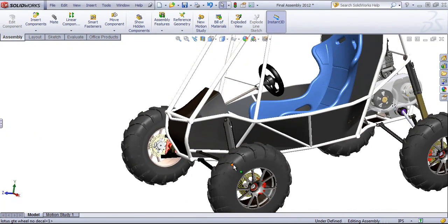While you see a solid model for these treads, I find the best method of creating treads for a tire or for similar usage to be creating a surface and then using a series of either a thicken feature or thicken cuts to create the treads.